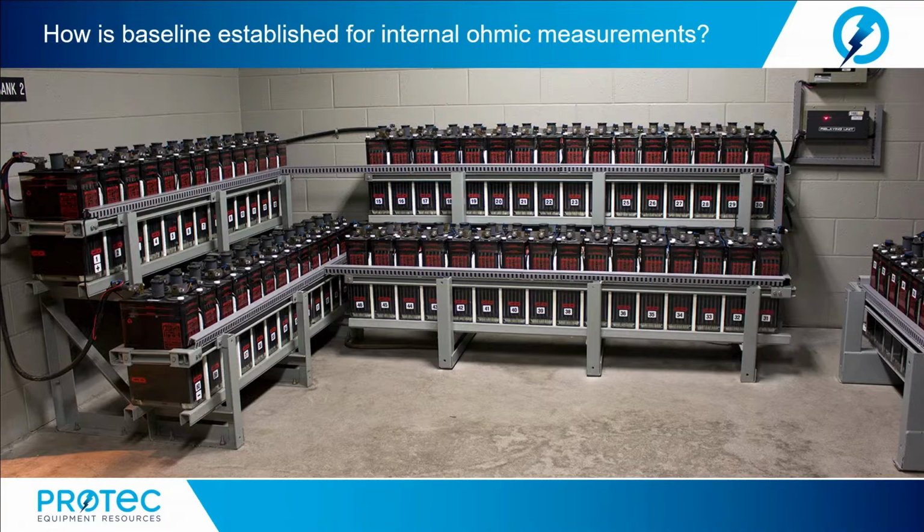However, often for older VRLA batteries, the owner of the station batteries has not established a baseline at installation. Also, for owners of VLA batteries who want to establish a maintenance activity which requires trending of measured ohmic values to a baseline, there was typically no baseline established at installation of the station battery to trend to.